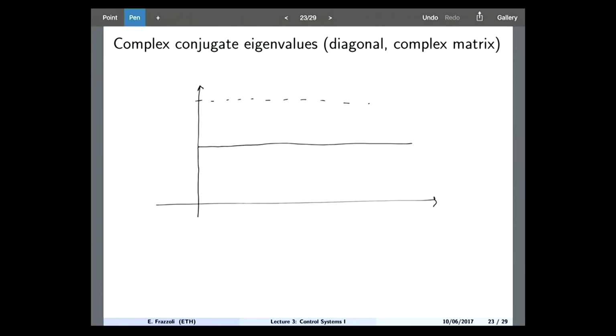So okay, you have a pendulum, right? But now instead of letting it hang freely, I apply a torque at the joint, okay? So I push it a little bit up, right? And now what do you think will happen? So now it will oscillate, but probably it will oscillate about some other equilibrium point, okay? The response will contain, in the same way as before, terms that match the natural dynamics of the pendulum. That is, it will contain terms that are an exponentially decaying sinusoid, plus terms that contain the input, right? Which in this case is just a step, you go from 0 to some value, okay?